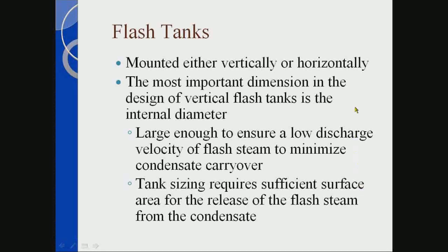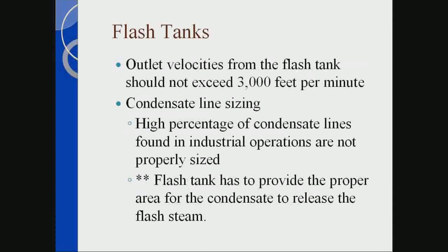One of the things that comes up quite a bit: if the condensate line is properly sized, then we'll get the separation of the flash from the condensate in the condensate return system. Unfortunately, most condensate lines are undersized instead of being properly sized or oversized. So we have to rely on the flash tank to do the separation of the flash from the condensate inside the tank.